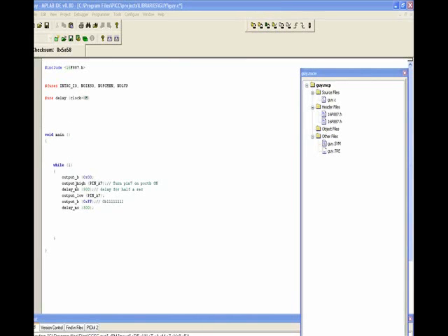It's telling us that we turn on, that is output high, pin 7 on port A, which I've commented here. So for posterity's sake, if maybe in 20 years time somebody should take this code, the person will understand because I've commented it. Okay, now you delay this for 500 milliseconds, which is half a second. So I've written here: delay for half a second.